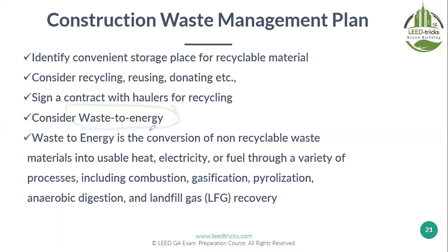So this is another way, accept it. But you don't burn immediately; first you do recycle, reuse, donate. Then send it to energy or burn it. Waste to energy is the conversion of non-recyclable waste. This cannot be recycled, so what will I do? I will burn it. Instead of sending it to landfill, burn it and get some power. And the output of burning these types of waste can be fly ash, which can be added to concrete. So you are using everything.